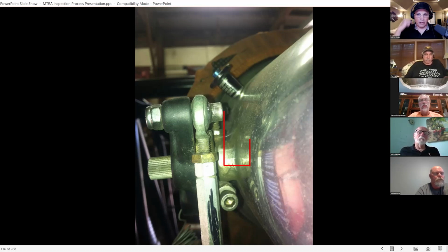For some reason, Enderle ships those things with that screw threaded into the black aluminum piece, and they apparently don't use Loctite because it's screwing into aluminum, so they have a tendency to vibrate loose. That's why we recommend putting in a longer screw that you can put a nut on the backside. So watch for that, because it's a tricky area. It's not a rule, but it's one of those things that we feel is pretty important and needs to be watched. Again, you see how the shaft is threaded. On some trucks, it's actually closer against the aluminum hat than what you see there.